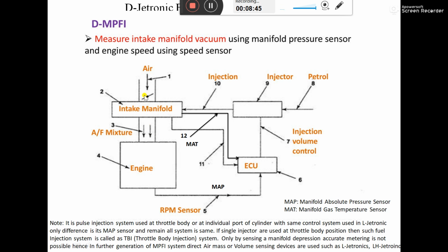Okay, so with respect to the opening of the throttle, the vacuum of the suction stroke vanishes as the barrier to airflow is removed by the throttle plate turning. So the vacuum changes with the throttle plate opening, or the pressure at the downstream area changes with the throttle opening. That thing gets sensed by the manifold absolute pressure sensor. Okay, this feeds into the ECU.